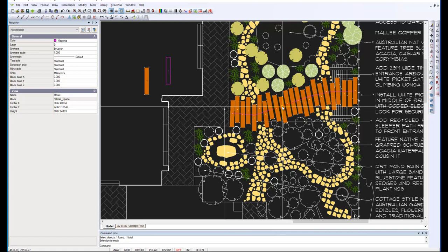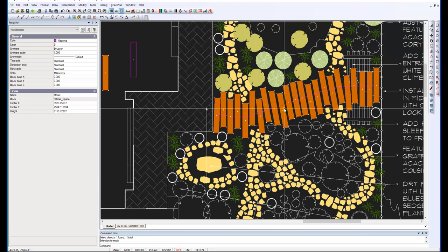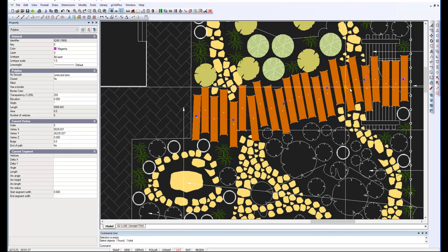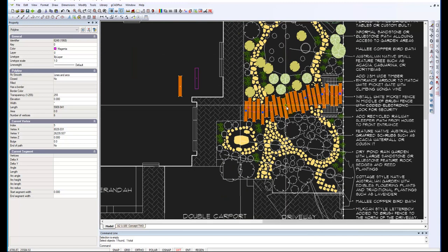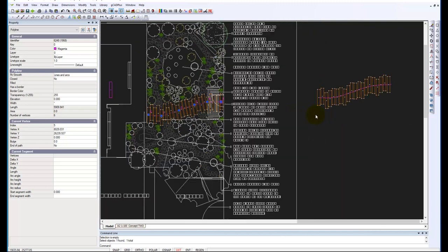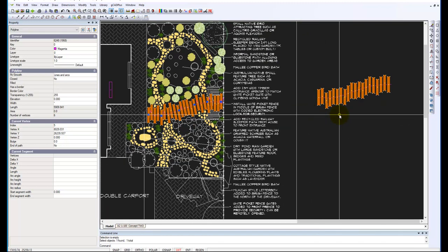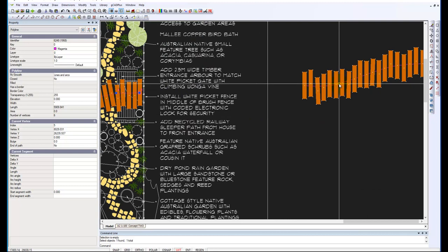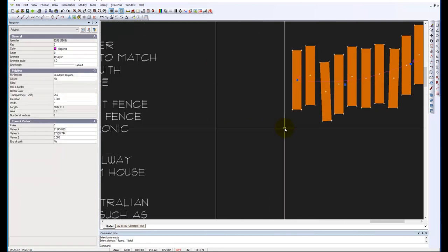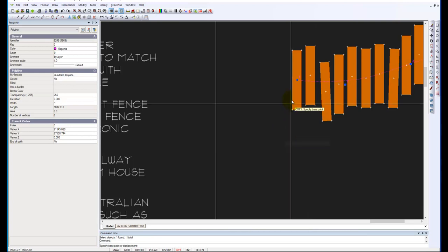You can, I think, make life even easier by drawing a polyline through the center of that path, and I'll just zoom out a little and come across and demonstrate how you can use the CopyAlongLine tool to let me latch onto the line. I'll copy that.